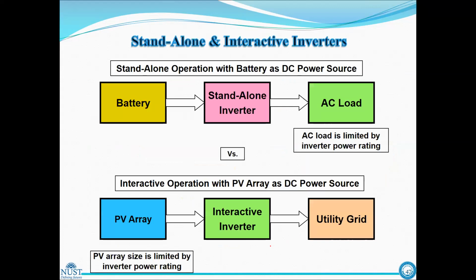Further, we should also distinguish these inverters based on the type of the power system. For example, for standalone, we must always remember that its input will be coming from batteries. So the battery should be sized as per demand of the standalone inverter. On the other hand, when we talk about interactive inverter, there is no battery or storage between.